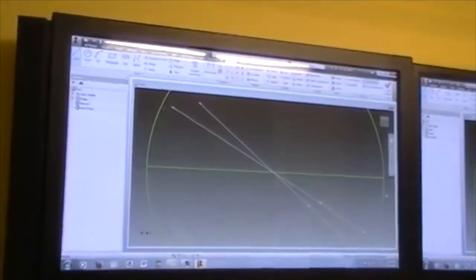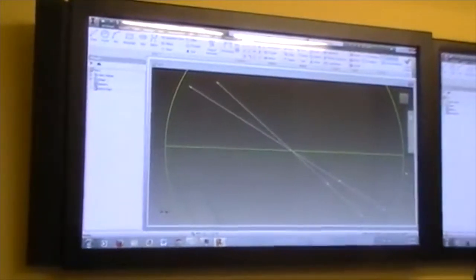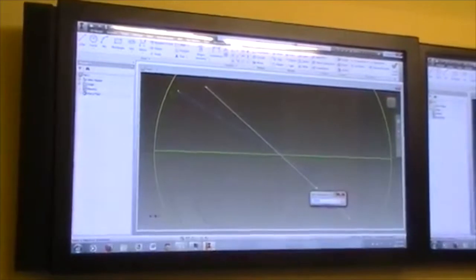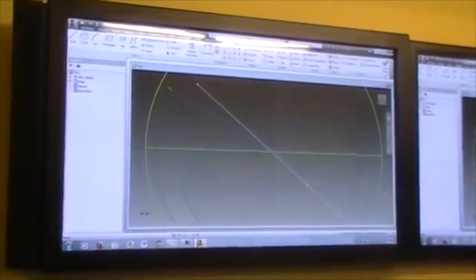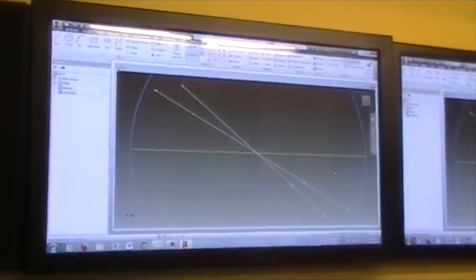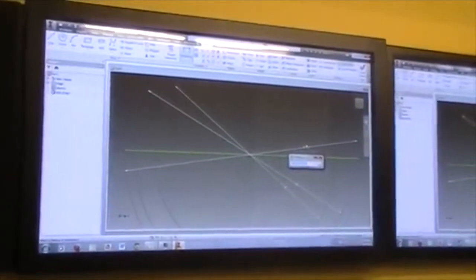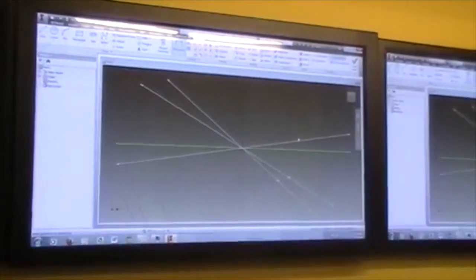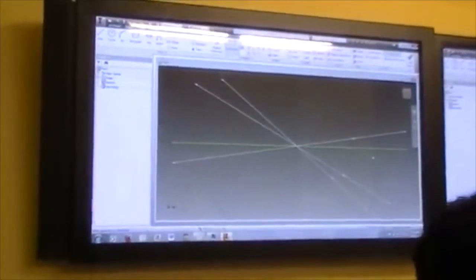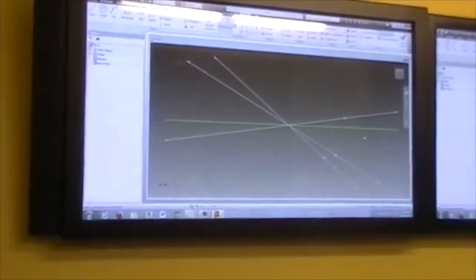So what you want to do to manually set the size of something once you've created it is, if it already has a dimension, you can double click the dimension and then change it there. But if it doesn't have a dimension, A, give it one. So now I've put a dimension on here, and then B, change the dimension. So let's make that a nice 65. Small change, but it actually will help down the road if you want to make something out of this geometry or you want to use it for something more complex.